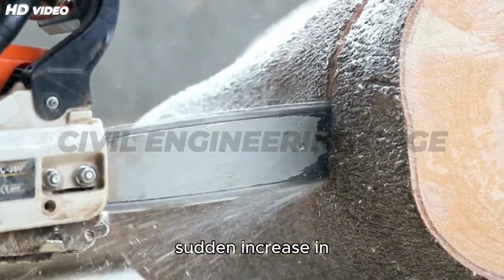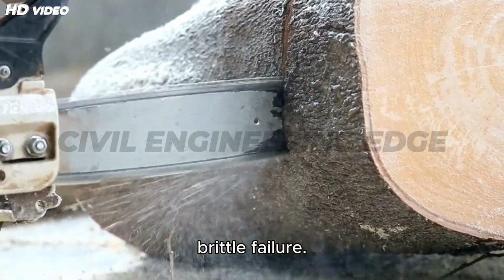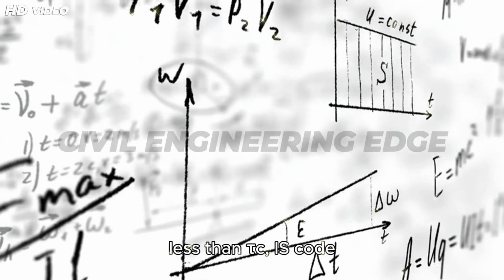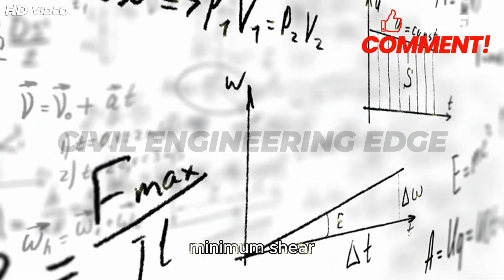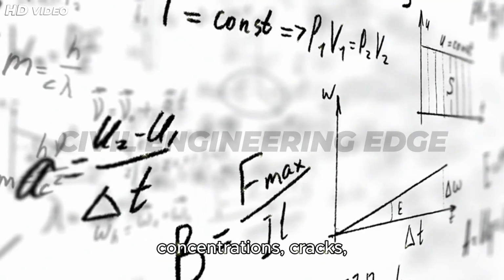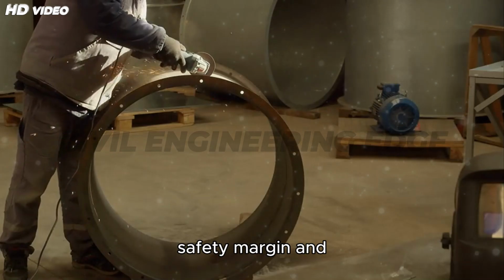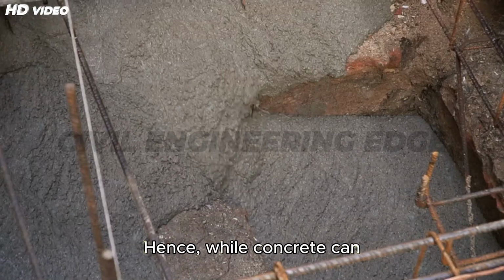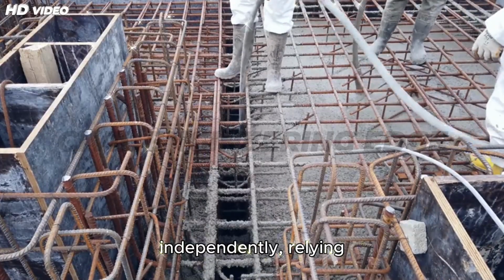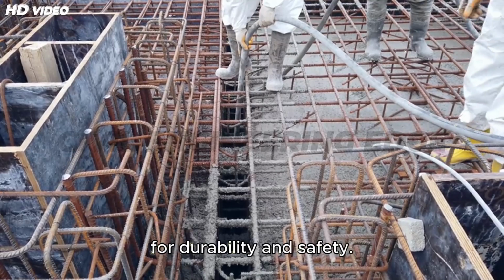Without stirrups, any sudden increase in load can result in diagonal cracking and brittle failure. Even if the calculated nominal shear stress is less than tau c, the IS code recommends providing minimum shear reinforcement to cater to unforeseen stress concentrations, cracks, and redistribution. This approach adds a safety margin and ensures ductile behavior. Hence, while concrete can resist some shear independently, relying solely on it is not structurally advisable for durability and safety.